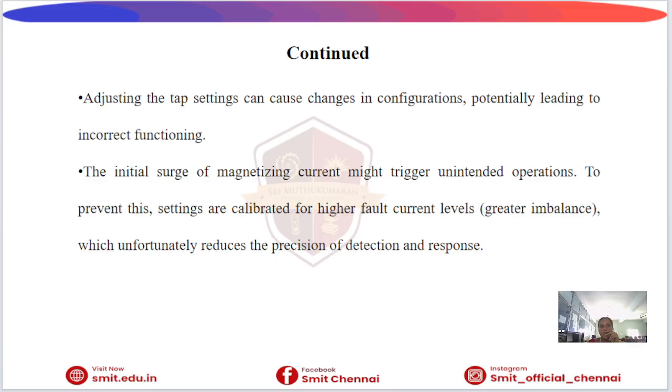Another limitation: tap changing in the transformer affects current values. This may lead to incorrect relay operations. High settings reduce sensitivity to small faults. So careful calibration is necessary in this scheme.